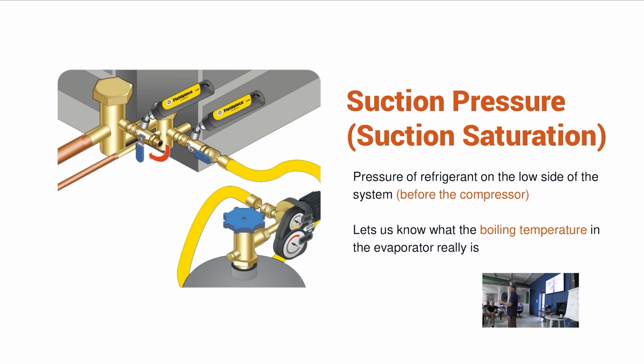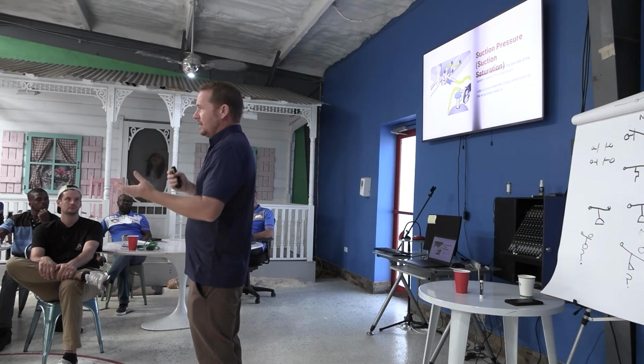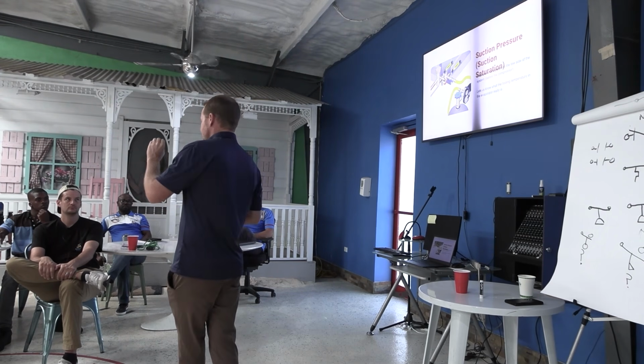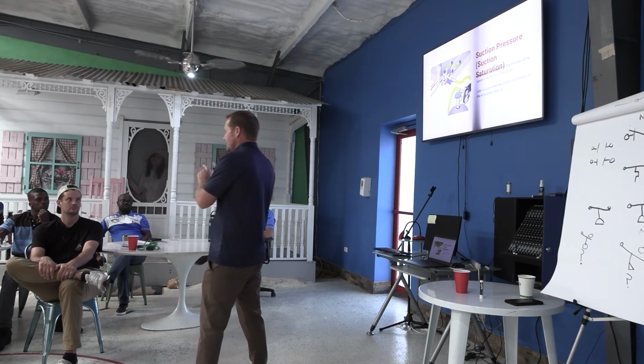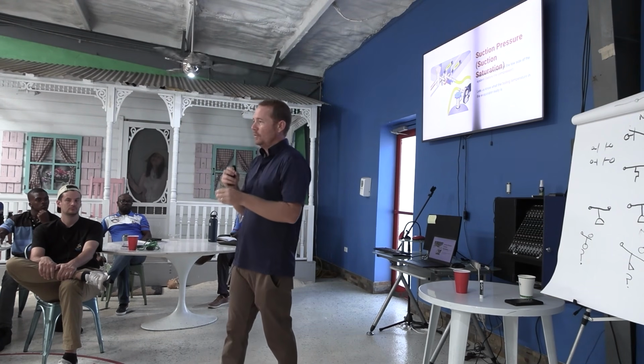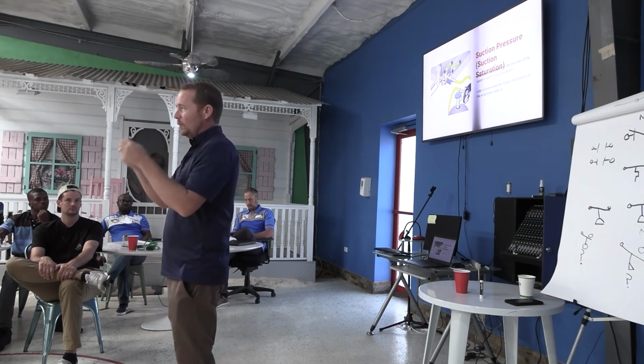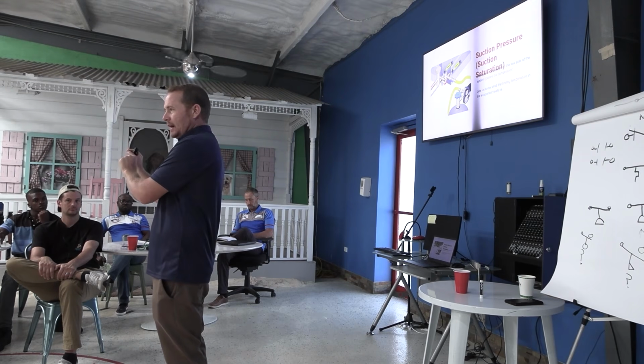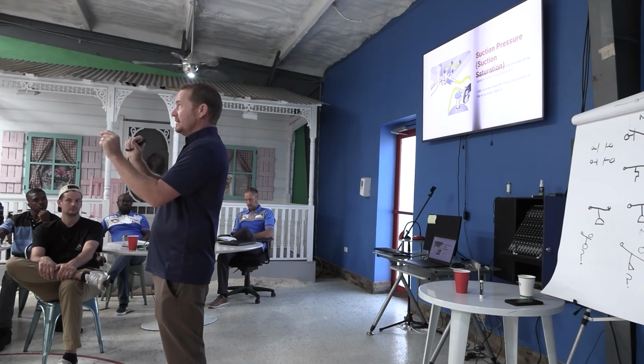But this is where a lot of guys get confused, because of this whole pressure-temperature relationship thing. It's like, well, yeah, but my pressure's this, that means the refrigerant is that temperature. No. It means the refrigerant is that temperature if it is in the process of changing state. And the way that I say it is, it's when liquid and vapor are present at the same place at the same time. At the same place at the same time.